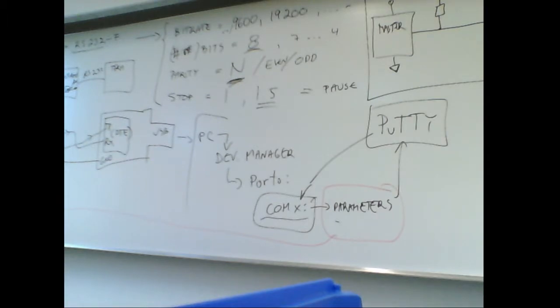Now, analog and temperature sensor. There, single value. And then C means sample and return data continuously, and X is stop sampling. Simple kind of interface.